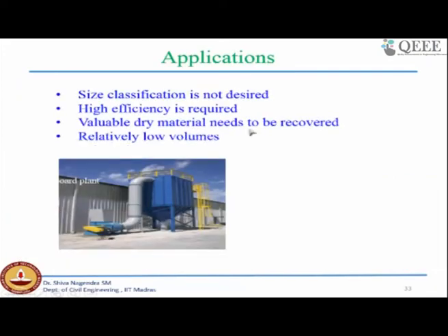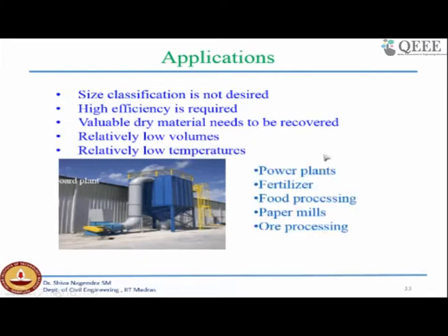So generally you will use the bag house if size classification is not required, high efficiency is required, you would like to collect some materials from your flue gas, and you want to treat a smaller volume of air. It is generally used in power plants, fertilizer, food processing industry, paper mills, and ore processing.